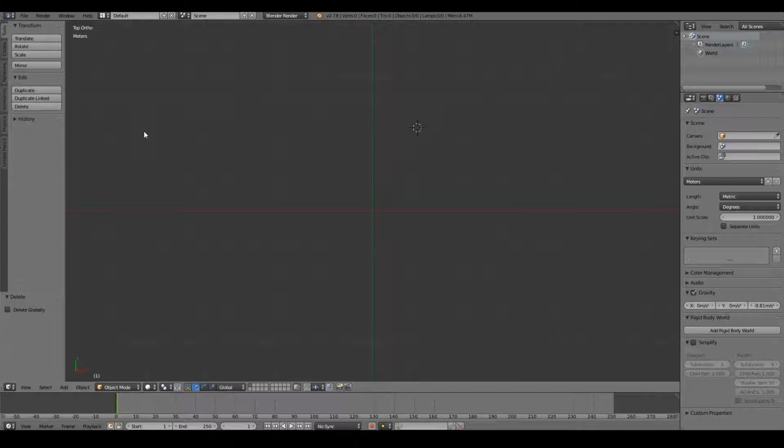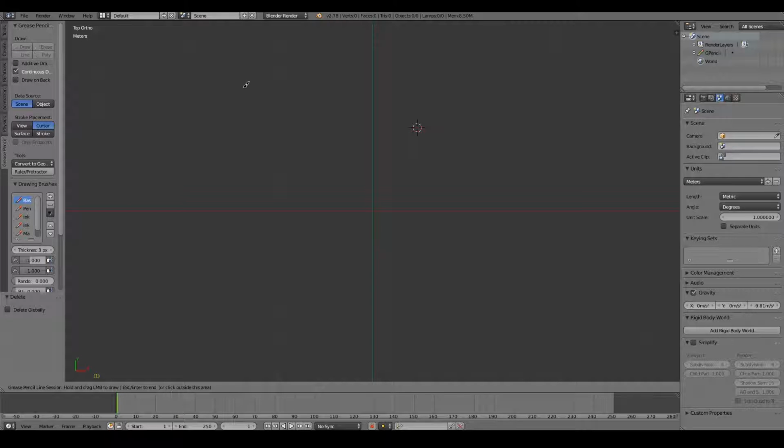To do so, I'm going to use the grease pencil and then enable continuous drawing. So this allows us to sketch on Blender instead of using GIMP. But one of the benefits of using Blender rather than GIMP is you can get real world coordinates. You can get the actual measurement, the actual sizes and things like that. So I'm going to press line, and let's just start somewhere random here. And I want to draw 1, 2, 3, 4, 5, 6, 7, 8, 9 meters length. Oops. And 6 meters wide. So 1, 2, 3, 4, 5, 6. So there you go. That is the average size of a garden.